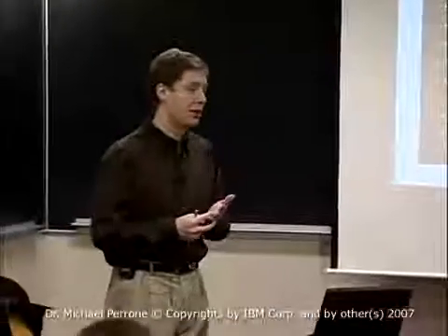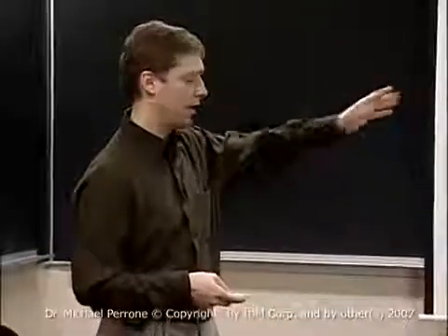And that was a design consideration from the hardware point of view, because as these chips get bigger and bigger, which is, if you can't ratchet up the gigahertz, you have to spread out. And so as they get bigger, flaws in the manufacturing process lead to faulty units. So instead of just throwing away things, if one of these SPEs is bad, we don't use it, and we just do 7. As the design process gets better, by the end of this year, they'll be using 8. The blades that IBM sells, they're all set up for 8.